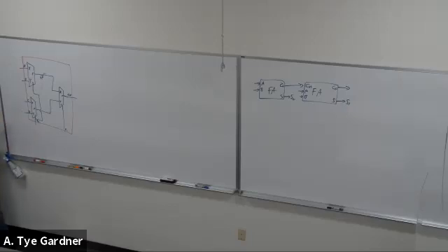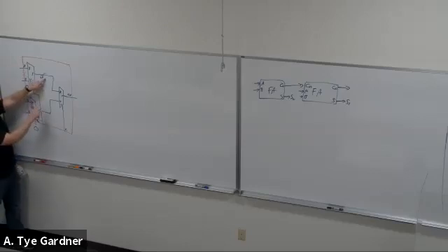Now, we'll talk about muxes in a little more detail in an upcoming lecture, but I just want you to get this into your head that the reason I'm doing this is if this select 0 signal is 0, then X, the A port, this first X, I'm going to call it A, is selected on this mux, and C is selected on this mux, okay? Because S0 is 0. So here and here, I have A and C respectively. And then the second bit, if it's 0, takes A, and if it's at 1, it takes C.